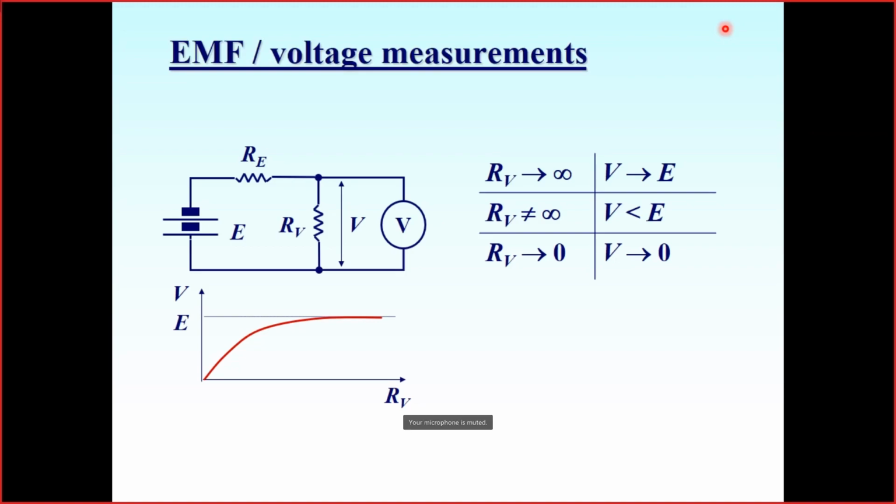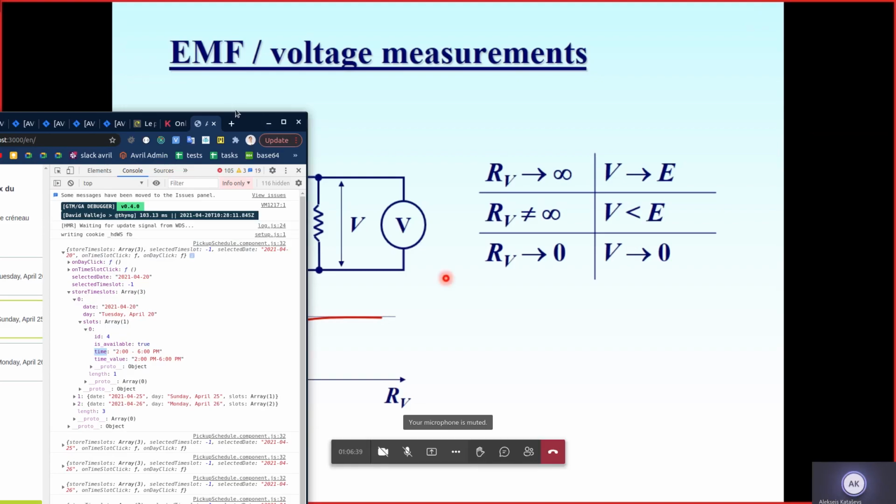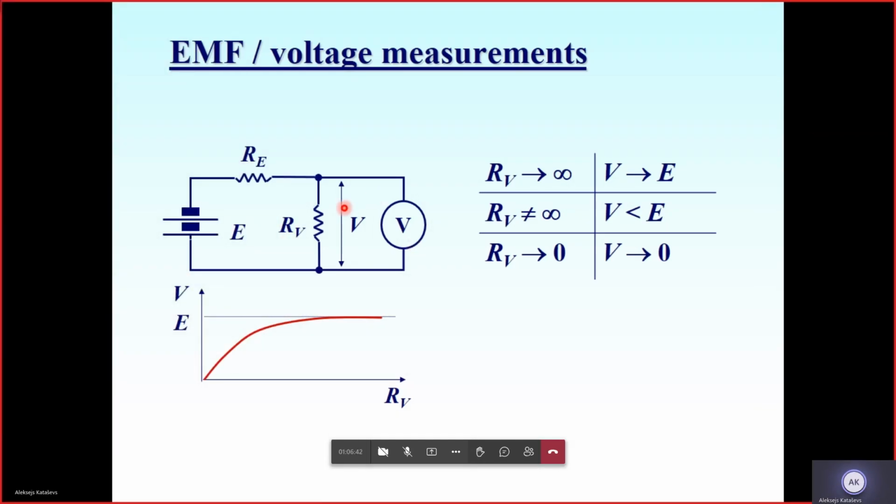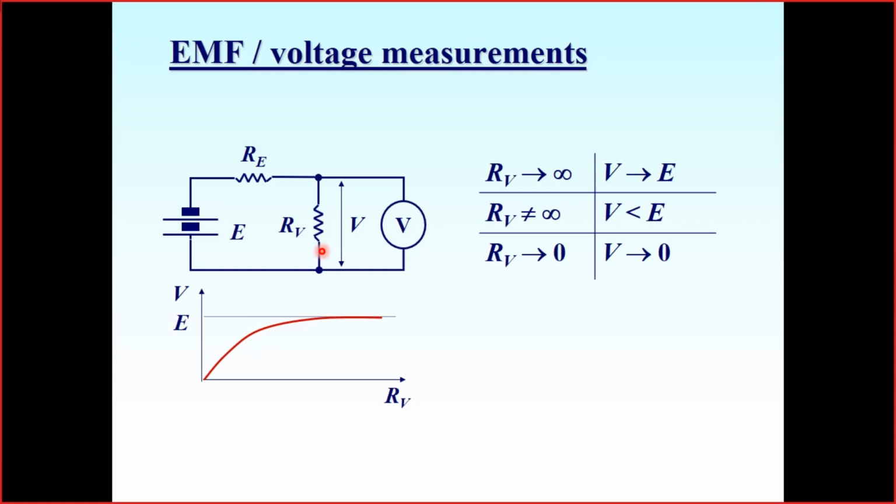The second part, what we're actually going to discuss in this topic, is the measurement of electromotive force, or voltage. When we speak about the measurement of the voltage from a source which has a quite high equivalent resistance, we should be careful because our meter with a limited input resistance may distort the measurement. We already discussed this when we discussed the input impedance: the effect of the voltmeter resistance on the measurement of the electromotive force of some small power element.